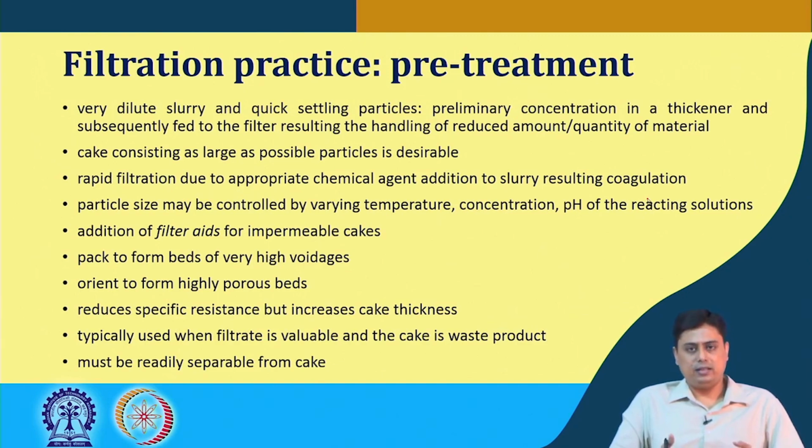Now, these filter aids have a basic property that they can form a bed of very high voidage. So, it is mixed with the suspension as a pretreatment, and then the whole suspension plus the additive or the filter aids are flown through the membrane. It reduces the specific resistance, but the cake thickness increases. It creates a packed bed of higher voidage, but the packed bed height increases. So, there is an optimum amount of additives or filter aids that needs to be added.